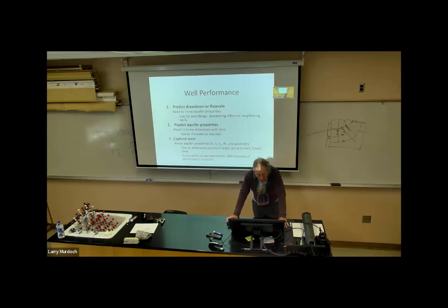Another thing that we're going to want to know is what's the capture zone of the well. The capture zone is the region where water that recharges an aquifer ends up going to a particular well. When we did that contour exercise in class, we drew out the capture zone of the well just by graphical construction. So we'll also want to be able to calculate that.